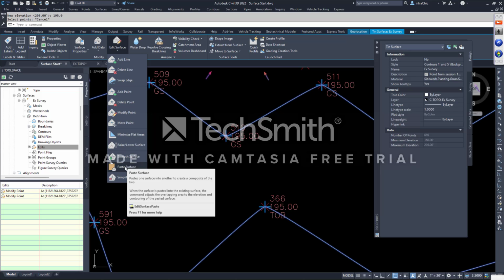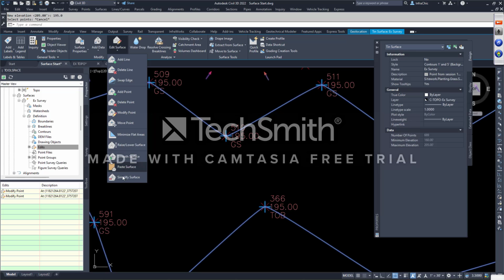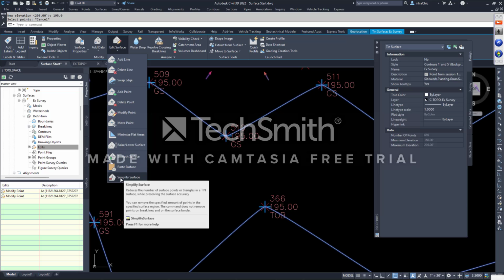It lets you bring in another surface, copy it. It's a direct link. When you paste a surface in, the other surface that you pasted, the original, remains as is. And it's a dynamic link. So if the original surface changes, then that pasted version will also change as well. It will update right along with it. It's not a static link, it's dynamic. There's also simplify the surface. It reduces the number of surface points in the TIN while keeping the accuracy. So those are your editable ones.